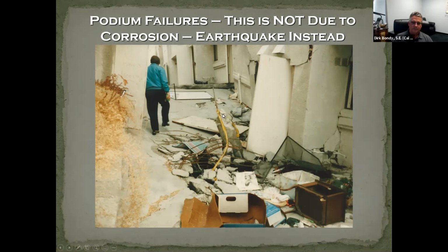But they got very lucky because the slab actually failed in flexure along this line, which turned out to be a great thing. You actually want that flexural failure. Had that not happened, there's a good chance this would have continued to unzip and continued to have punching shear until the entire building came down.